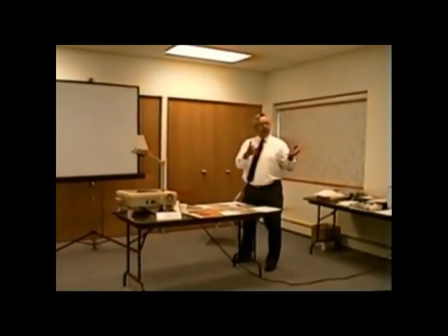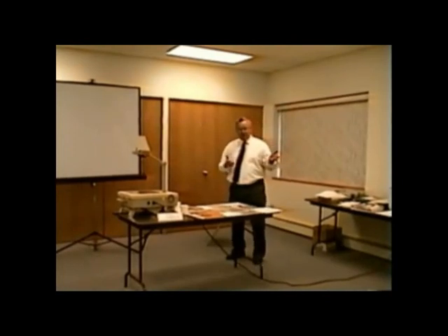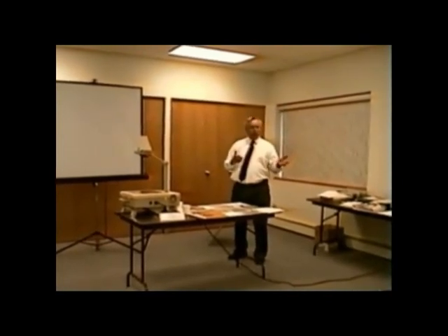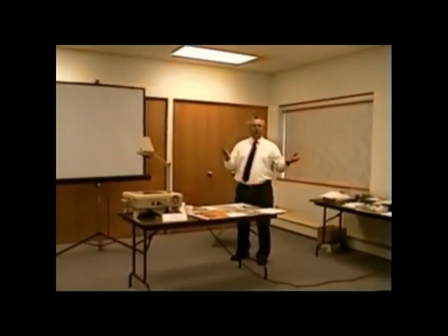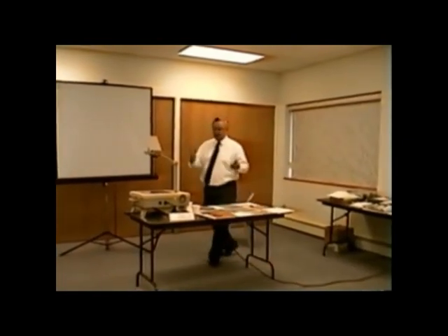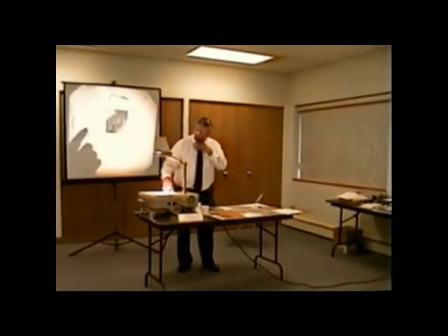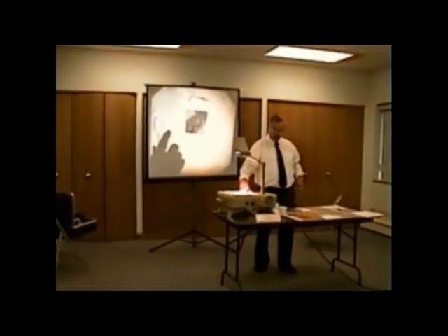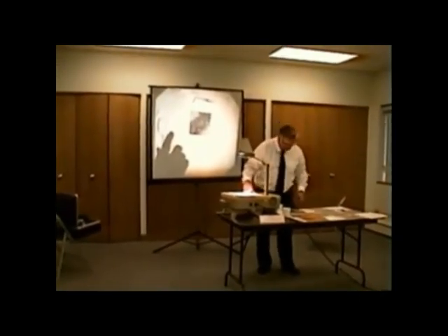So when we ask the contractor, the technician that's out there, what are your microamps? And he says, they're okay. How does his eyeball see microamps? You can't. You need an instrument. You need a digital readout. So I hope you understand that when you light that furnace, you're going to get anywhere from 2 to 4 microamps, and it even improves a little bit after 5 minutes of runtime.